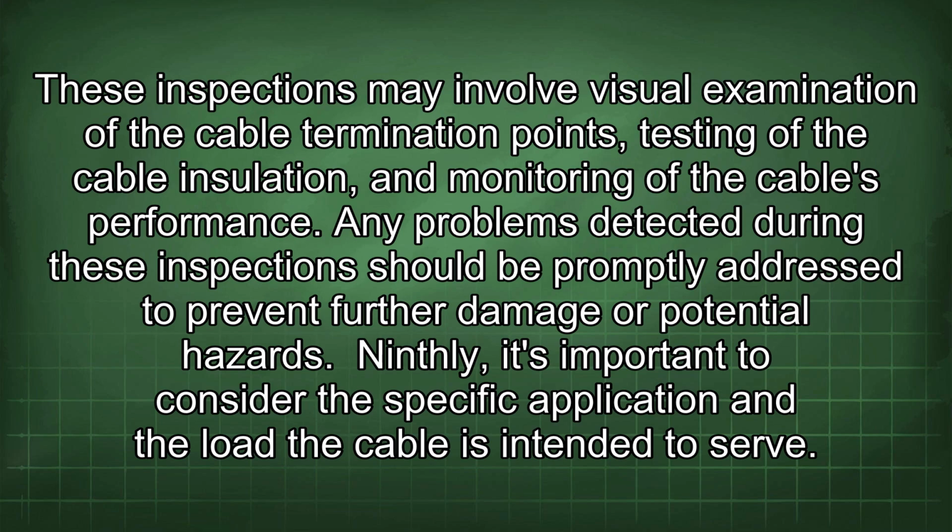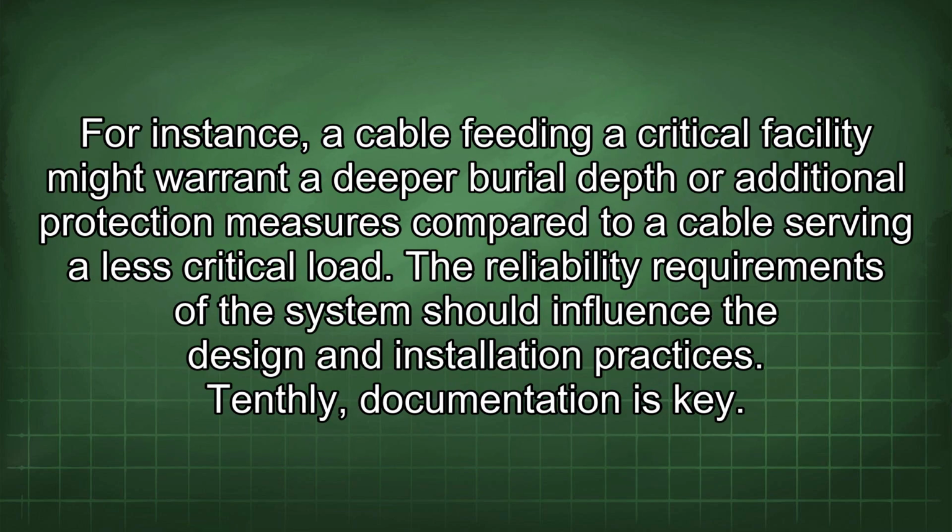Ninthly, it's important to consider the specific application and the load the cable is intended to serve. For instance, a cable feeding a critical facility might warrant a deeper burial depth or additional protection measures compared to a cable serving a less critical load. The reliability requirements of the system should influence the design and installation practices.